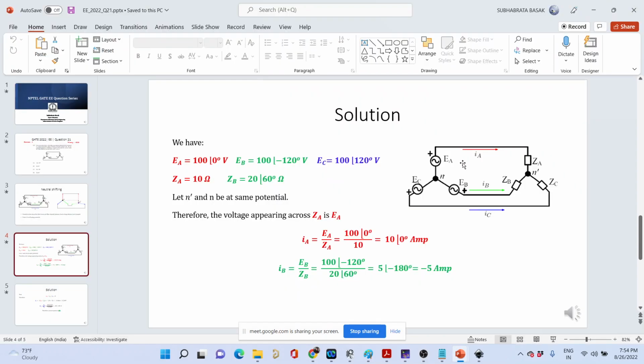Well, in such a case, when the loads are unbalanced and you need to find IA, IB and IC, what you can do is write the KVL equations for all the three loops, and then find IA, IB, IC. That would be a very tedious process. The other method is finding the symmetrical components of IA, IB and IC by drawing the positive sequence, negative sequence and zero sequence current. In that case it would be a very tedious sum.